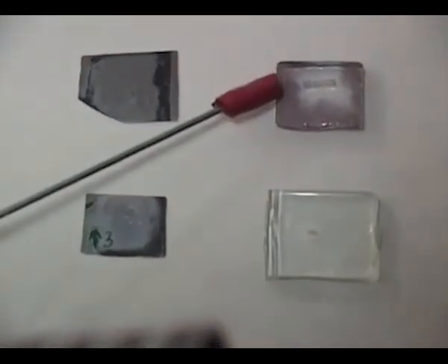This energy of the spark is utilized for carving microchannels in different shapes. So here 4 samples are placed, 2 are glass workpieces and 2 are silicon workpieces. These are treated at 50 volt DC supply between cathode and anode. Cathode is 200 micrometer copper wire, anode is graphite rod, and 2 small channels are there. These need further magnification to see properly. That is why we have carried out scanning electron microscopy to study these channels.